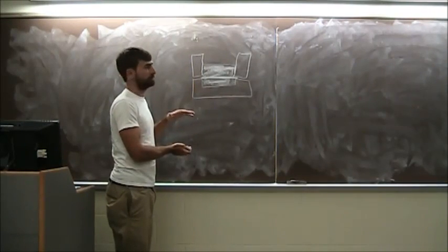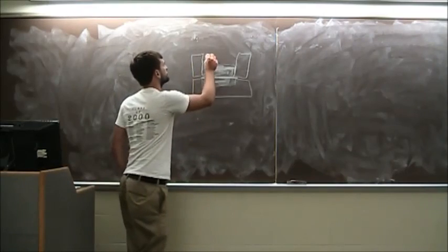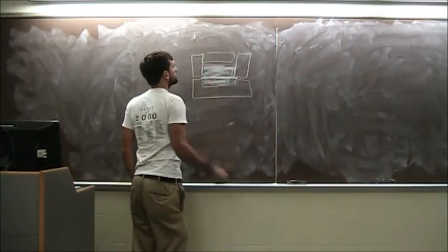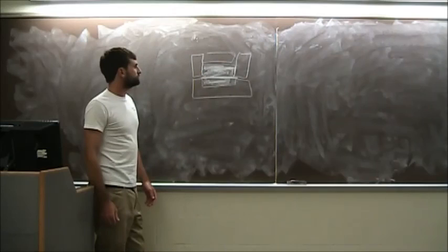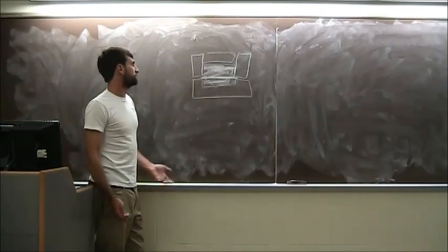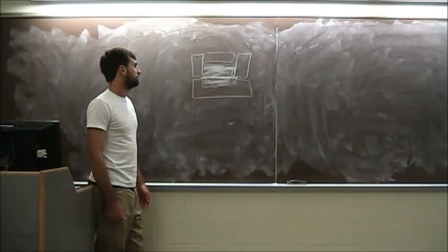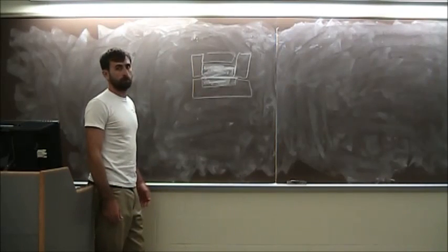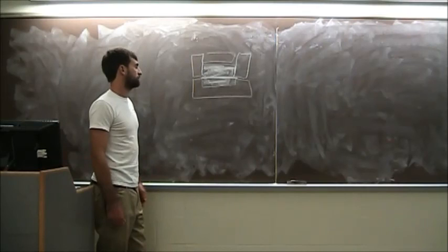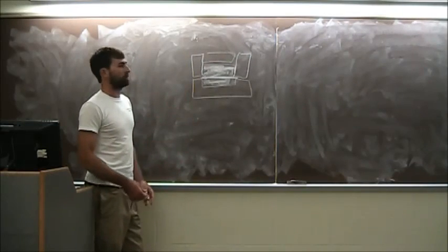They're not isotropic materials. So that's one thing that is kind of a disadvantage of this test. But it depends on what your sample is. If it's some clean, fairly uniform granular material, then that's probably a good estimation of that.